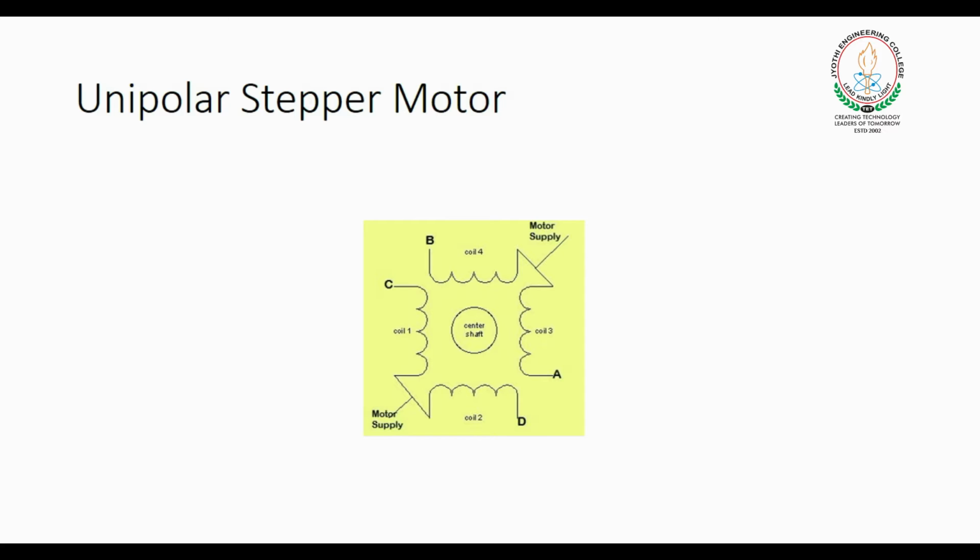Today we will discuss full drive mode. In this mode, two electromagnets are energized at a time. So the torque generated will be larger when compared to wave drive. As we said earlier, power consumption is higher than in the other modes.